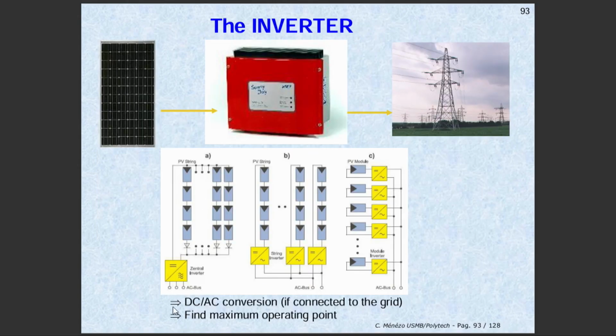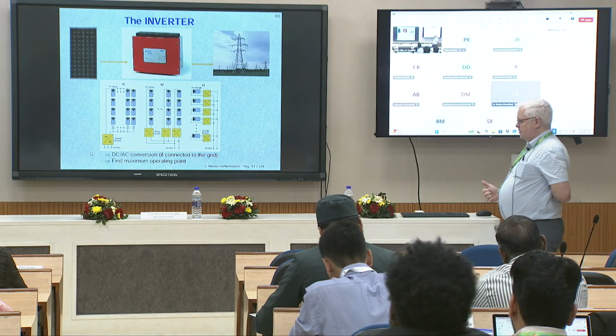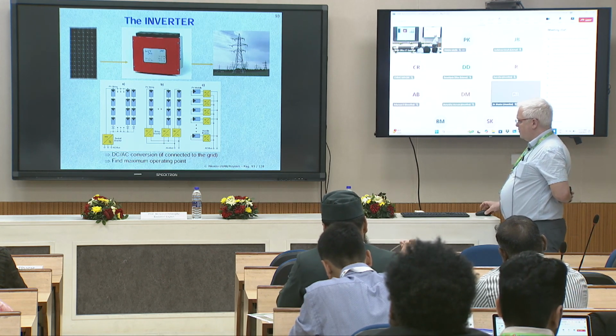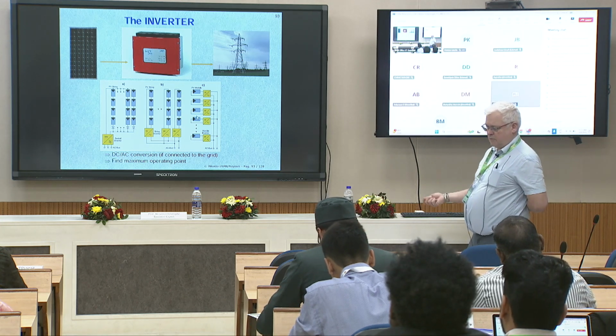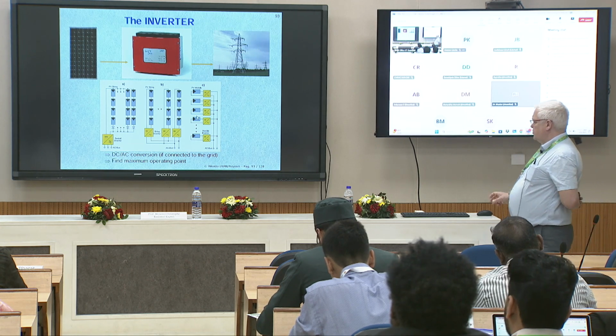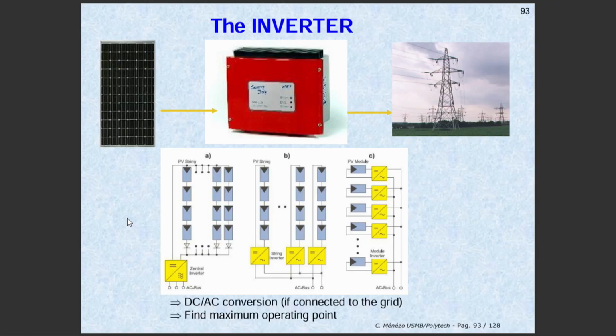We have finished on the way to connect the inverter to your PV central. We have seen that the main advantage to have one inverter for the whole central is the price, but the other advantages are in favor of multiplying the inverter in order to avoid, if there's a problem on the PV central, generating a mismatch effect and then a bad production or a breakdown of the whole PV central.